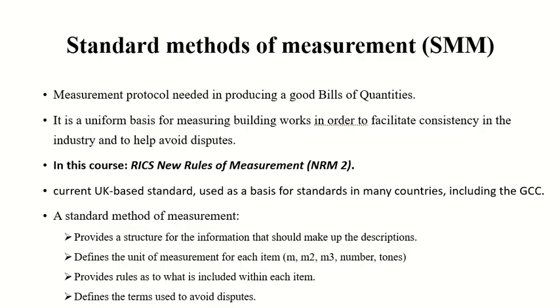So what means what? I showed you about concrete, that we write the concrete as C20/something something. What does it mean? Strength, cement strength, and maximum aggregate size. So what does each thing mean? It is from the standard method of measurement. So nobody can say that if there was 20 written, I don't know what 20 means. So I took any value of strength? You cannot do this.